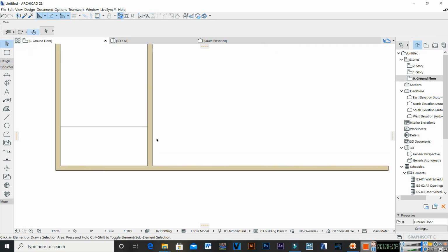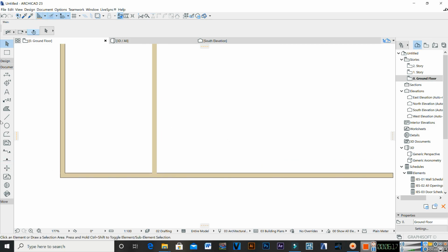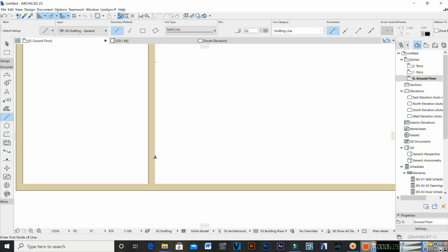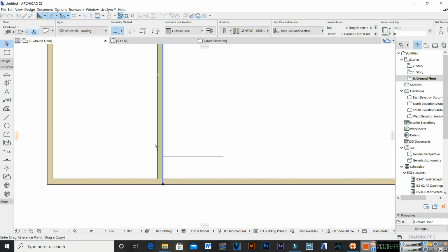Now we want to put the entrance to this living room. We don't want it to be here directly, we want to put it here. So we just make a veranda here, for instance, maybe 2.4 meters wide. Type it again, 2.4. This is the line. Make sure after you have copied the wall, you can delete the lines. This is just to make the work easy.